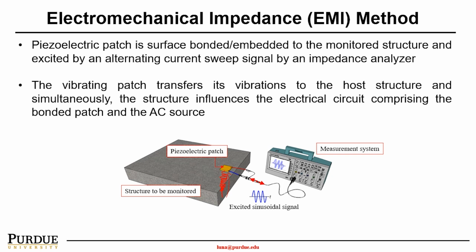The reason it is called electromechanical impedance is that we specifically look at mechanical impedance, which is the force over velocity of this particular wave, of course, over time, the derivative of them. And so therefore we can understand the material's stiffness and the material's defects.